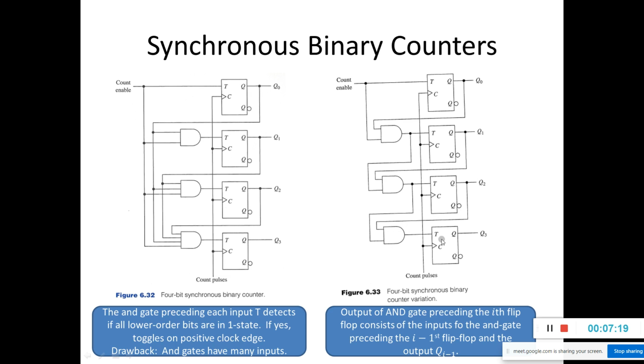So all the flip-flops are positive edge triggered T flip-flops. They will toggle if the input is 1, the count enable is 1, and the clock is rising from logic 0 to logic 1.